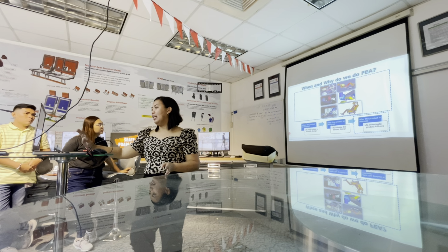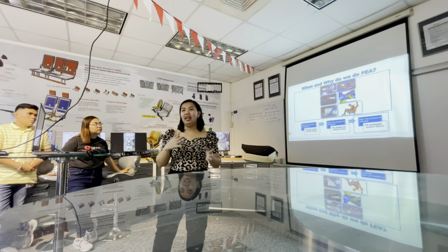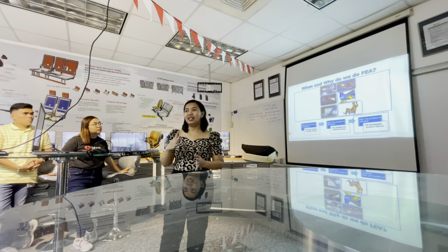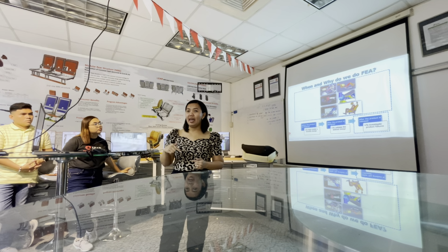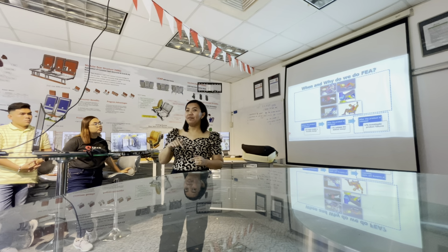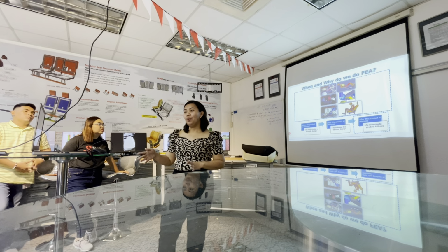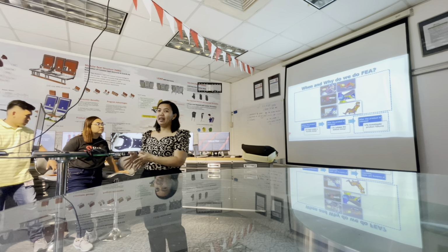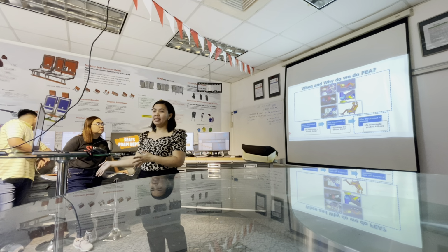So last but not the least, after the product is released, we investigate product failures, especially if in FEA we do a series of validation. After that, we do the physical test. Once there are failures in the physical test, it will always go back to FEA to see why this failure is not predicted. So that's the time we investigate. We try to investigate and then correlate our model, and then from there we create a model from that failing part and we do the improvements.